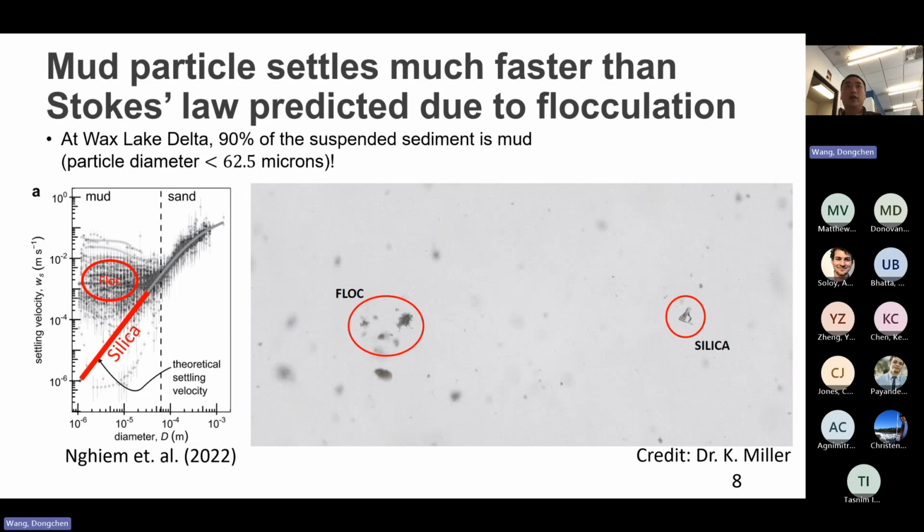One main issue is that sometimes fine sediments are not transported as individual grains, but aggregate together, because finer particles tend to have organic matter on their surface and form sticky flock grains. Once these fine particles form larger flocks, these flocks can have almost the same size as sand.